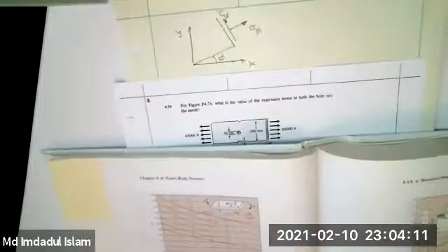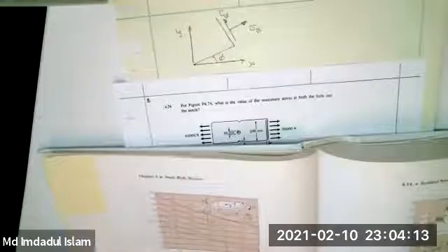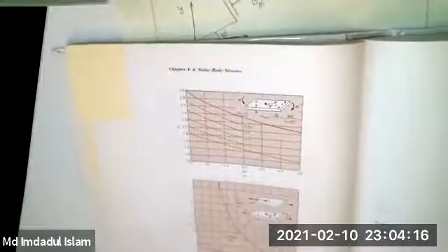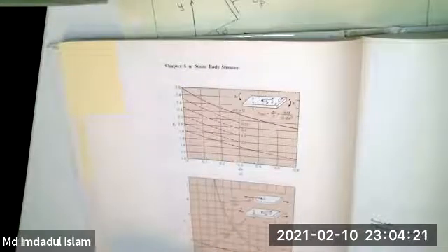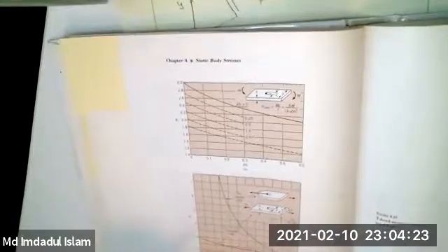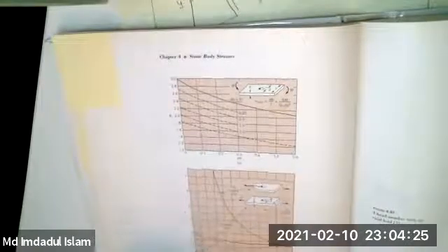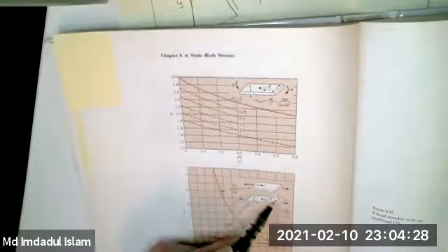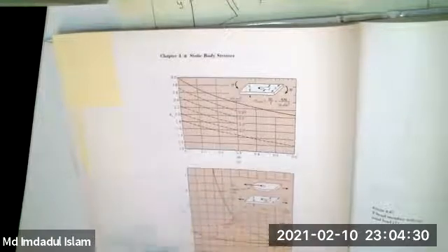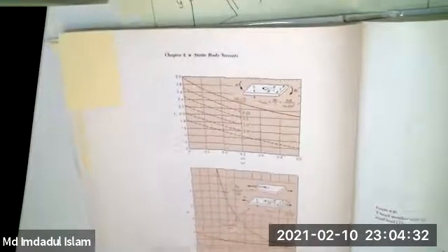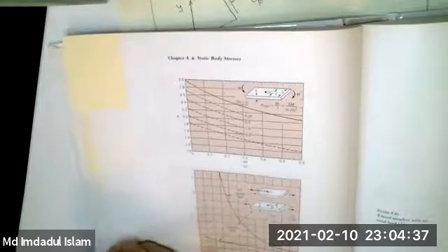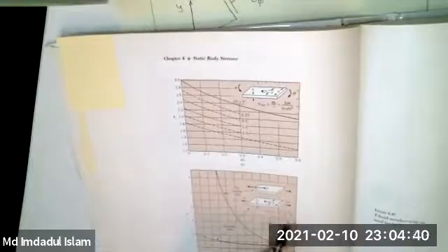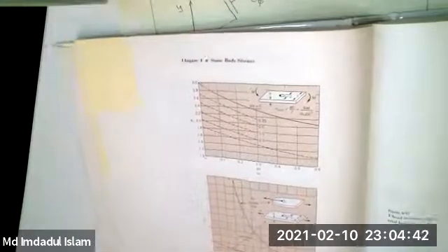Here's the plate with the hole. Down here, you have to go get D upon B. Well, these charts have their own notation. They're not even consistent from one chart to another. So you have to read on here what D is and what B is and what H is. Although these results are independent of H, basically. Well, the nominal stress is not. And so that's done in the worked solutions.